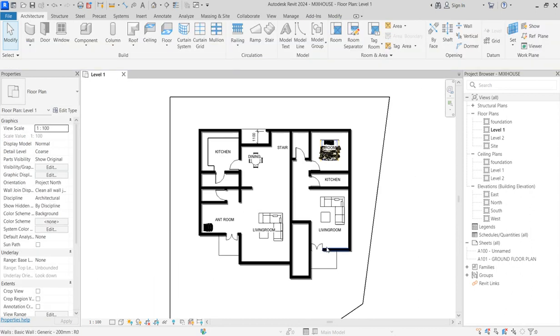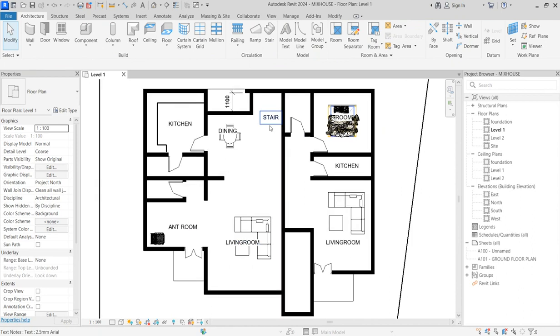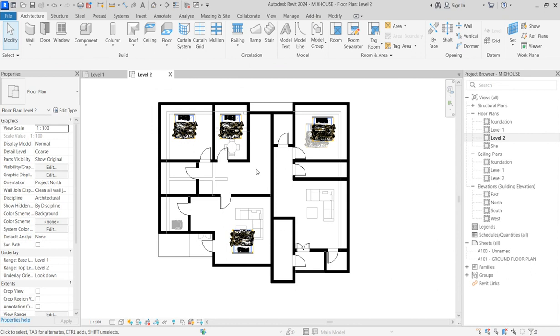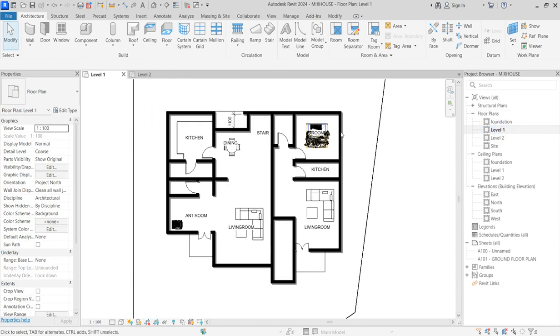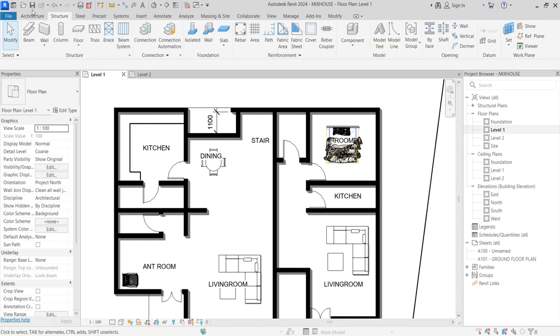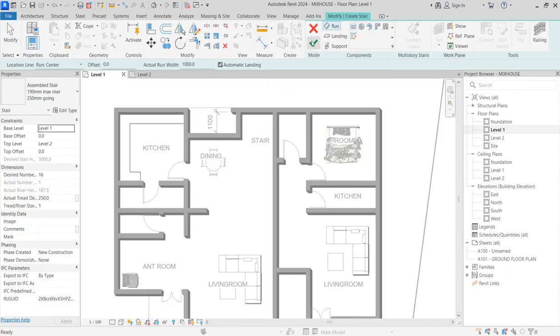And today we want to create the staircase for all this so that the structural activities of this will be taking shape. So let's move on. What we'll do is go to stair by setting the structure. Go to Architecture, then you come to Stair from here. So it's something straightforward.